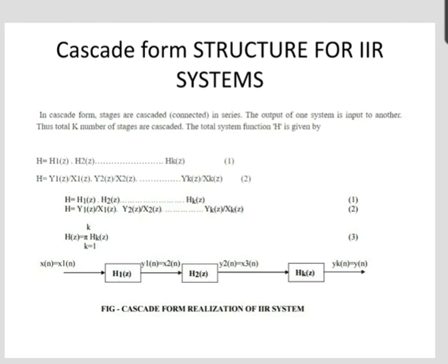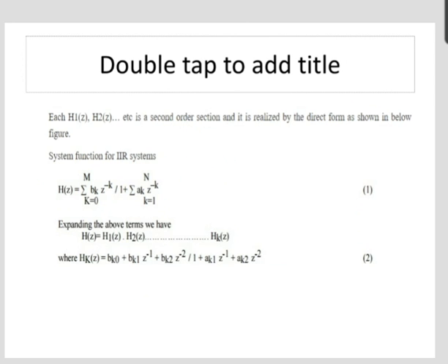This is cascade form realization of IIR filter. Each H1(z), H2(z), etc. is a second order section and it is realized by the direct form. The system function for IIR system is given by H(z) = summation k = 0 to M, and by expanding the above terms we get H(z) = H1(z) H2(z) ... Hk(z), where Hk(z) is bk0 + bk1 z raised to minus 1 + bk2 z raised to minus 2 ...